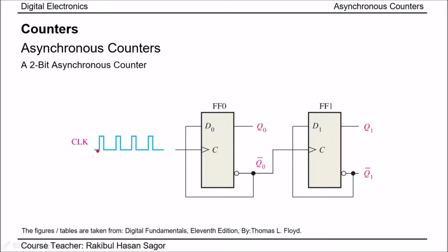So what happens in every clock pulse triggering, first one output is fed, then when Q0 becomes 1, then 0 output is fed. So every clock pulse triggering, we get the toggling output using this D flip-flop. Similar thing happens for the second flip-flop, but for the second flip-flop, the clock pulse is taken from the Q prime output of the previous flip-flop. That means the main strategy to make this type of counters is to have the toggling operation in each flip-flop.